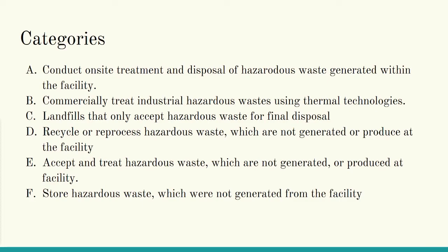Category C. Landfills that only accept hazardous waste for final disposal. For the final disposal, facilities that accept only inert or treated hazardous waste for the final disposal in the dedicated cell. Facilities that can accept hazardous waste for final disposal such as solidified, encapsulated waste under Class K of this procedural manual.